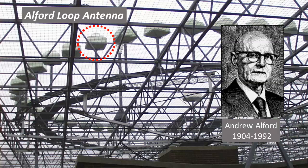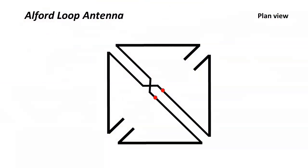He worked on many antenna designs over the years, including broadcast antennas, and he was involved in development of the first ILS. In the 1940s, he received a patent for this antenna design for use in navigation systems. The Alford loop has the useful attribute of omnidirectional, horizontally polarized radiation in a fairly simply constructed and quite broadband arrangement.